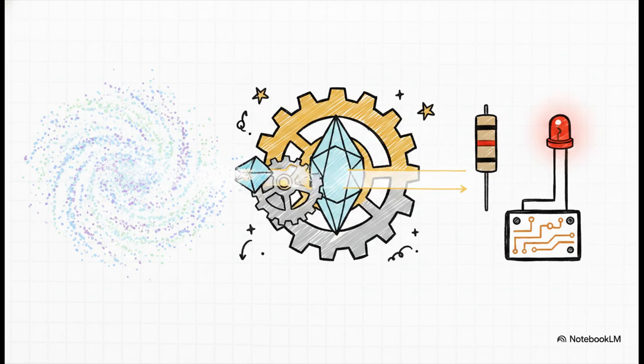Take a classic mass spring damper system. The differential equations governing its oscillation and decay are structurally identical to those governing an RLC circuit. You know, a circuit with a resistor, an inductor, and a capacitor. The math honestly does not care if it's describing mechanical force or electrical voltage. By spotting this isomorphism, we translate abstract rules into a physical electronic setup. This circuit isn't computing the equation, it's simply behaving according to it. It's a pure analog translation.